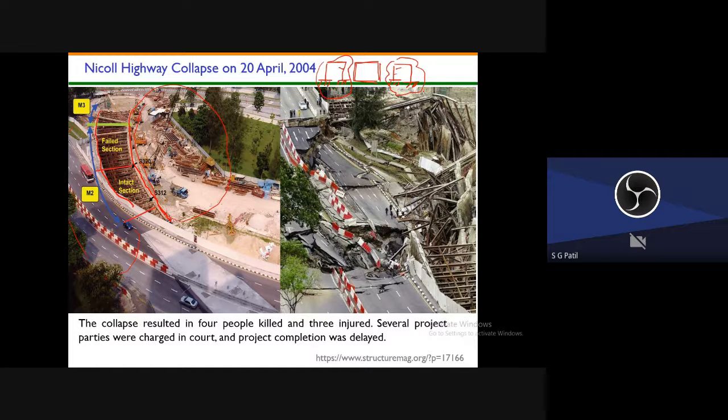How will you safeguard all these surrounding structures? There is hardly any space between your upcoming structure and the existing structure, so you have to retain the soil very adjacent to these structures, almost at a 90 degree slope. A 90 degree slope is not possible to make in soil, so that's why you have to build these retaining structures.